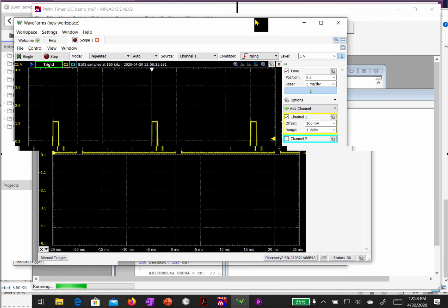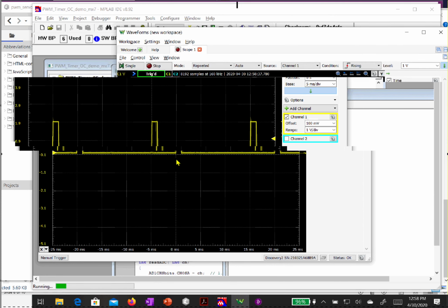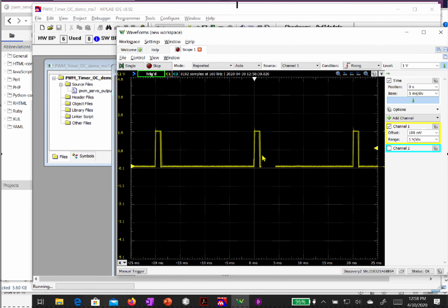Okay, so what we're doing is we're generating pulse width modulated signals using timers instead of the output compare. Could we use the output compare instead of the timers? We could. The only thing we need is to ensure that we connect those outputs to the appropriate driver circuitry so that we provide the appropriate power inputs to the motors so that we can drive them.